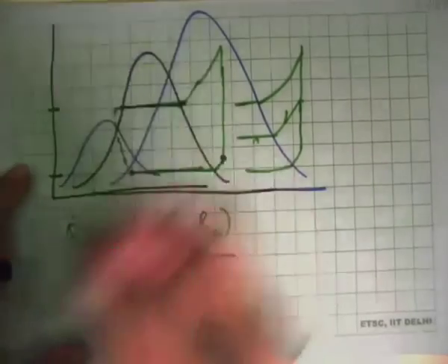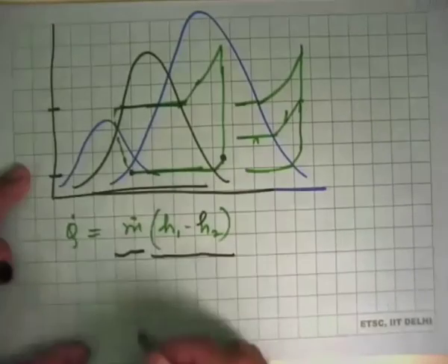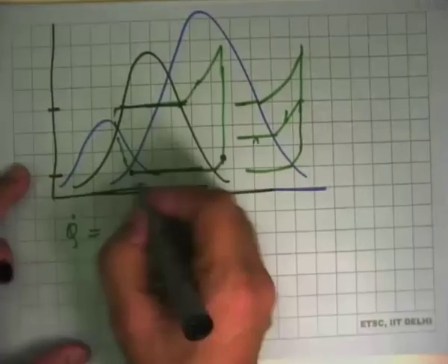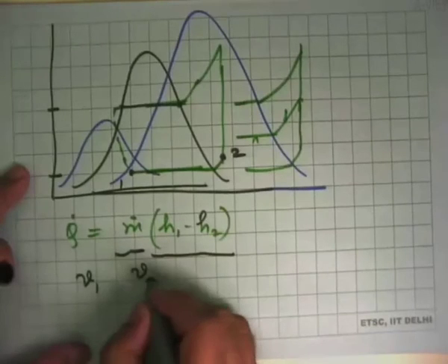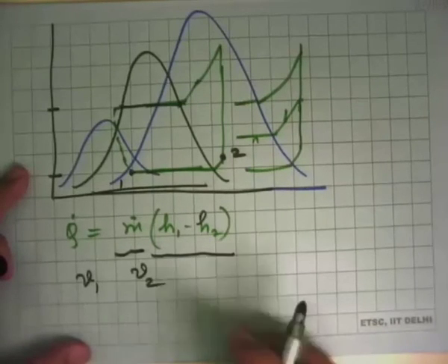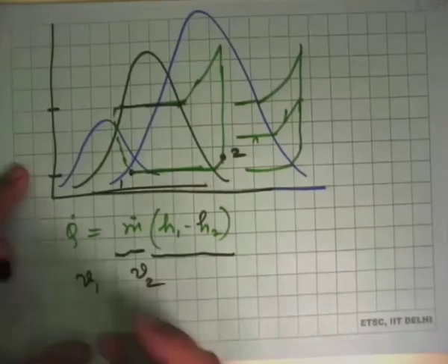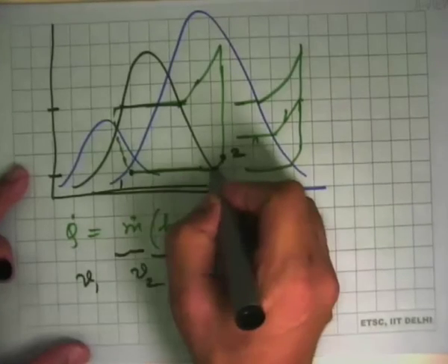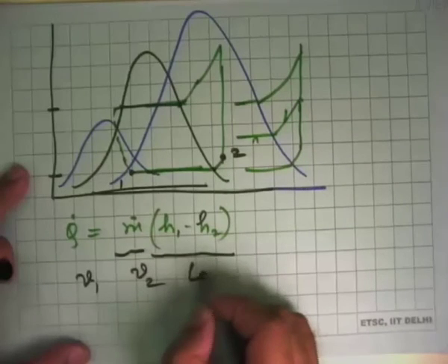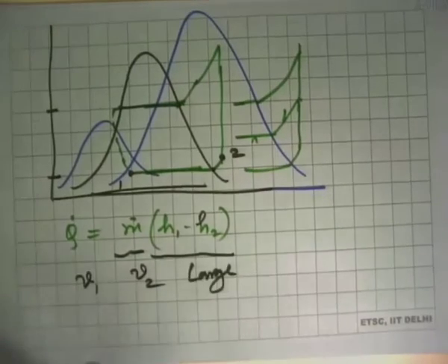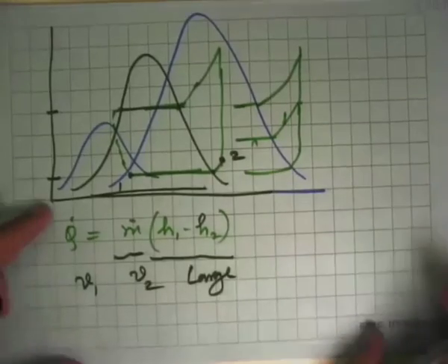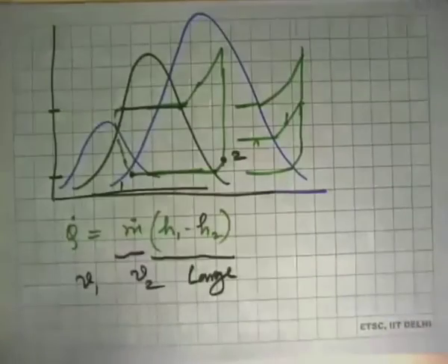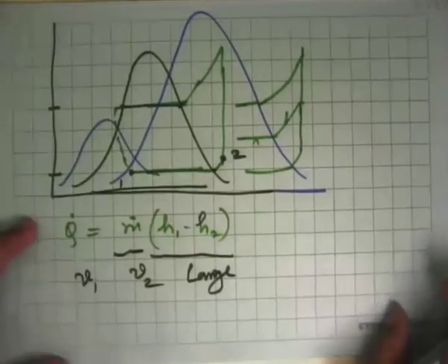But you look at the other properties now. So you ask that, this is my first part, how big will be my equipment, and say, well, what is the specific volume at these two states? This is 1, this is 2, and you go back and pull out V1 and V2. And you will see that for water at 6 degrees Celsius or 5 degrees Celsius, dry saturated vapor here, V2 is huge. That means the specific volume has become so big that I need a very, very big pipe to make this thing flow, and that becomes impractical. Unless we are able to control it and redesign the machine to take care of that, then we can do it. So we say, well, water is not very good.